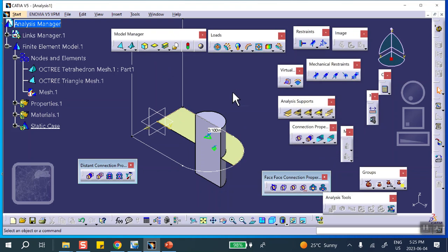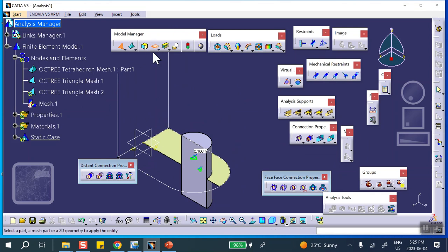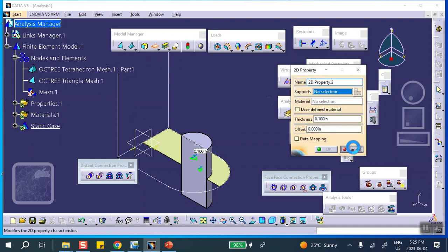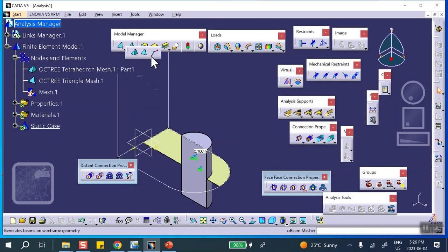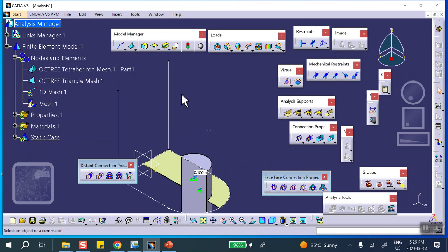Okay. Now we're going to mesh this beam. Don't worry about that. Don't mesh this because it should not participate. Cancel that out. Let's try it again. Beam. Right there. And I'll use still 0.2. No problem. You know what? I'm going to make this even smaller, 0.1. I don't have to, but I want to look at a different size mesh. That's fine.